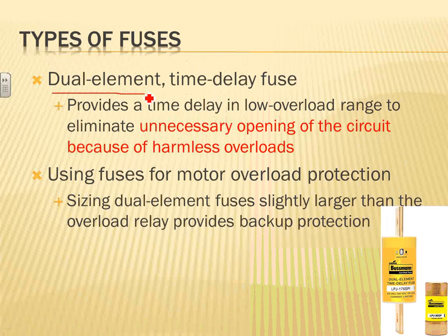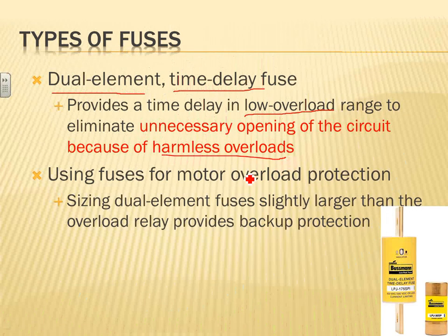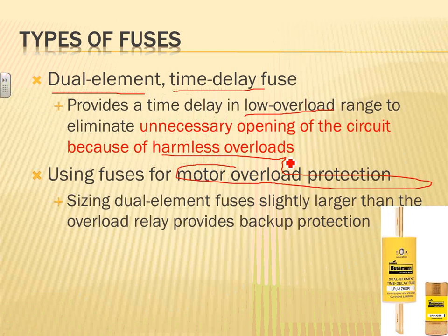So dual element time delay fuses are a good application for motors. We'll talk about motors, guys; next meeting we're going to be talking about motors. It provides overload range, avoids unnecessary opening of circuit breakers because of harmless overload, and also provides overload protection as a backup. One element, as you know, is rated to give you backup for overload protection. I'm not going to talk about overload versus overcurrent because we're coming on Thursday. That's going to be the topic for motors.